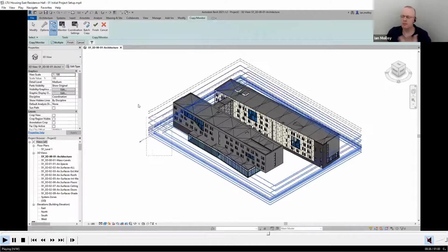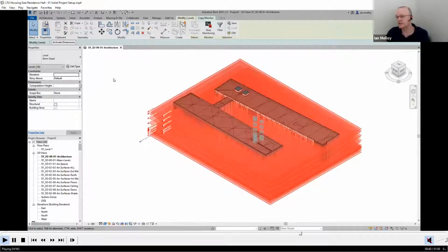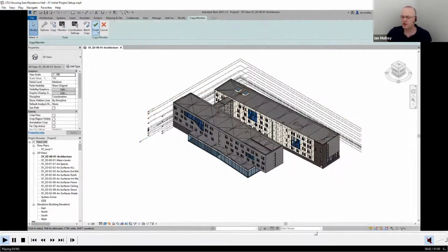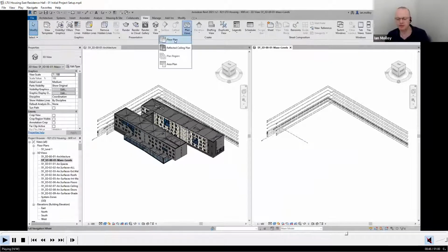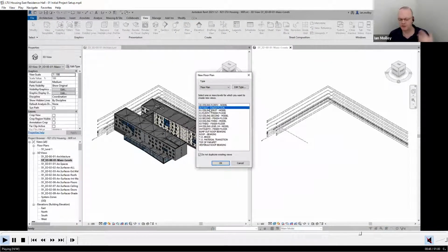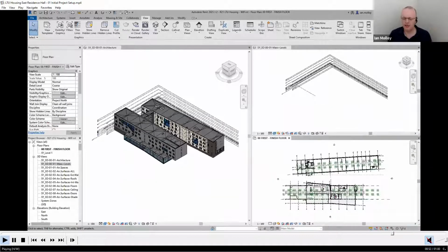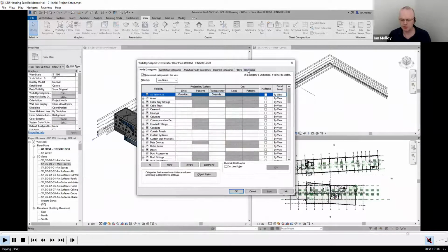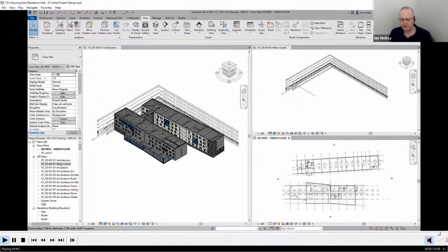So this whole example and workflow really works from the very earliest stages of design. Even though we've got a detailed design that we're starting with here, I'm retrospectively going back and asking what it would look like if we did a conceptual energy analysis, schematic model, and so on. So what I've done here is I've created a new Revit model linked in the architectural model. I'm just setting up some views so that I'll be able to work in. So the architectural model as a reference is on the left and my views are on the right.